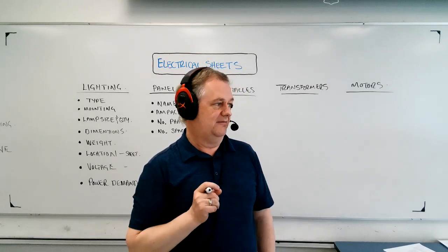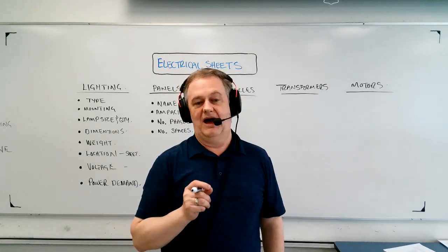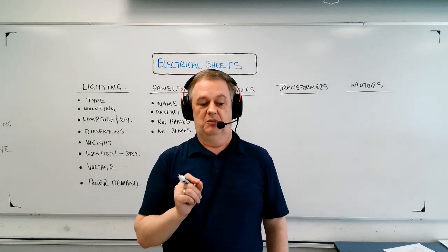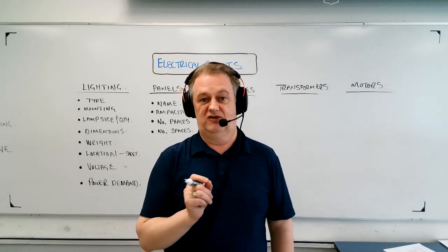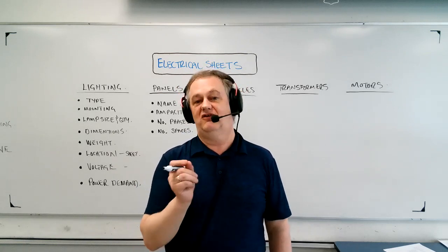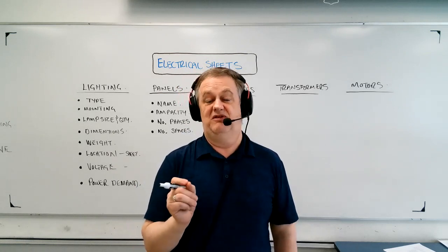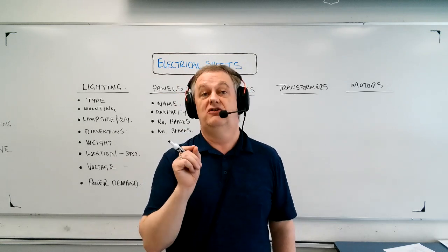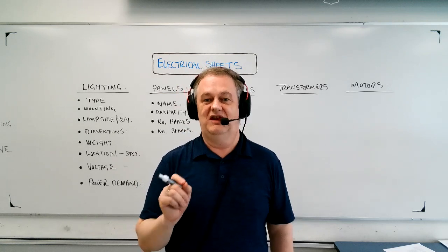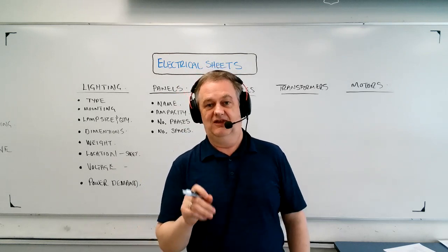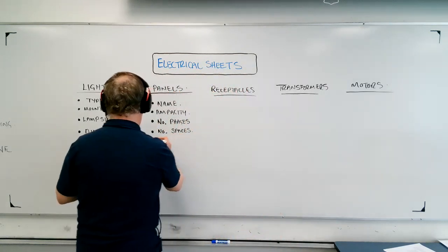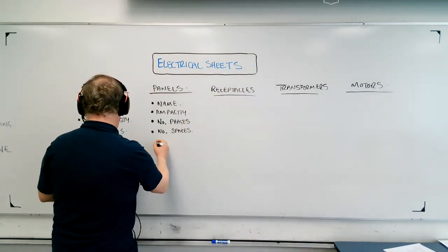Now, what happens in many cases is people design breakers that will provide 2 circuits from 1 space. So you could actually increase the number of circuits that can be fed from a panel, but you can't increase the number of spaces. That's something that comes from manufacture. So the number of spaces is given in the panel schedule, okay?